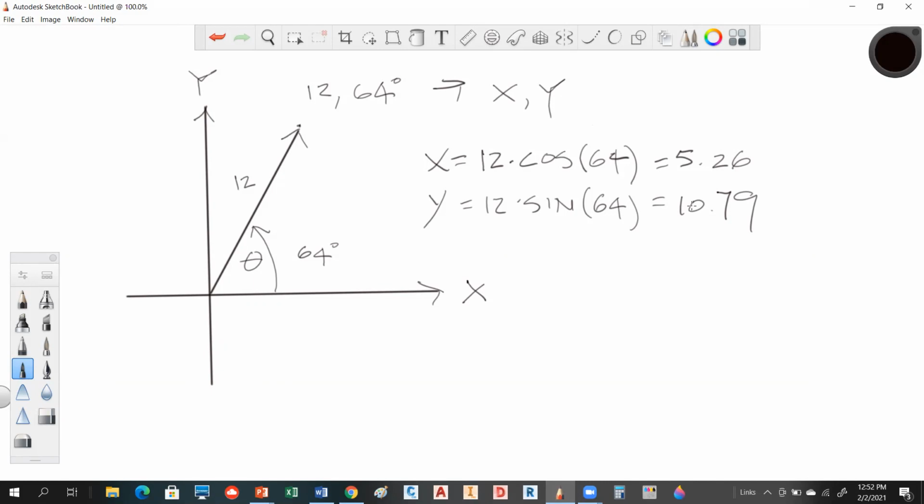Yeah, that's right. There's something that's really different though. Does anybody know what's different about these equations? Look at your angle. Where's your angle being measured from? From X, yeah. It's from the x instead of the y. So this equation, notice this is the x cosine relationship, but for us, this would be departure. You see that? Does everybody see that? But if you notice, when I defined latitude for you, we used the cosine for the latitude because we actually use this angle here.